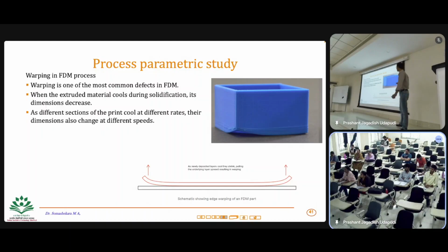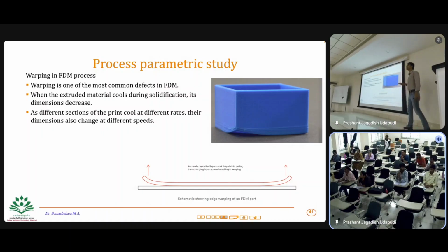If you don't fuse it or liquefy it, it will not go and stick to the bed, so eventually it will come away. You need to have enough temperature, enough in terms of melting temperature, so that it will go and stick to the bottom. That is where I think many people make major mistakes. The first 3 layers are very important in this technology.